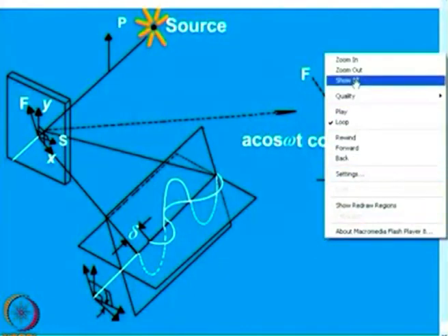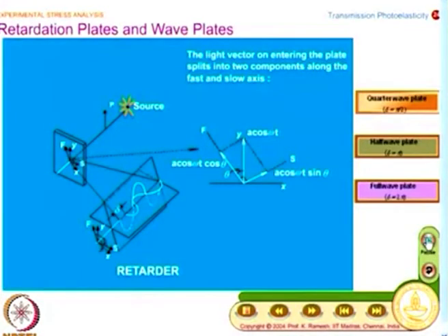If I have two simple harmonic motions which are mutually perpendicular, if they have a phase difference, depending on the difference in phase, you will see lights of different states of polarization, and let us see that. So, I will have a light ellipse coming out of the model. I use model and crystal plate interchangeably, please pardon me, and a model behaves like a crystal plate when stressed. In a crystal plate, it is naturally having birefringence, that is the only difference.